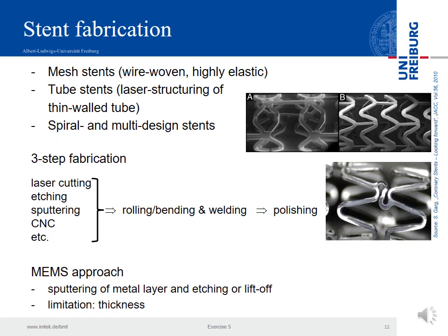Everything has to be polished, so that you don't have sharp edges or residues that enhance foreign body reaction of the stents while being in the body. MEMS approaches are rare. You could imagine sputtering of metal layers and etching or lift-off, but the thickness is not that high that you can really use it for mechanical support of those vessel walls.